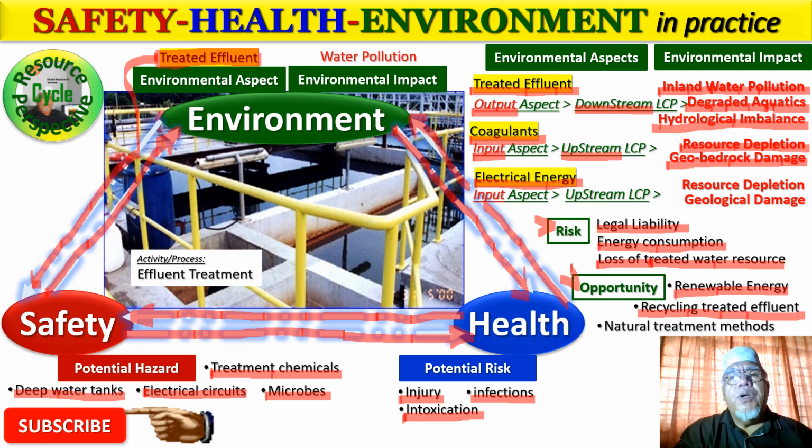On top of that, we tap rainwater harvest. Okay, and in the future, not to say in the future, I have already preached this since 1999, and some companies are doing it also, but despite the effort, there are some problems with the agencies over here, because I am looking into treating water, industrial effluent, using natural plants like duckweed, like water hyacinth, because we have studied mangrove plants. The mangrove roots are able to absorb a substantial number of heavy metals, and somebody is studying the mangrove leaves, which can be used as one of the membranes in a reverse osmosis technique.